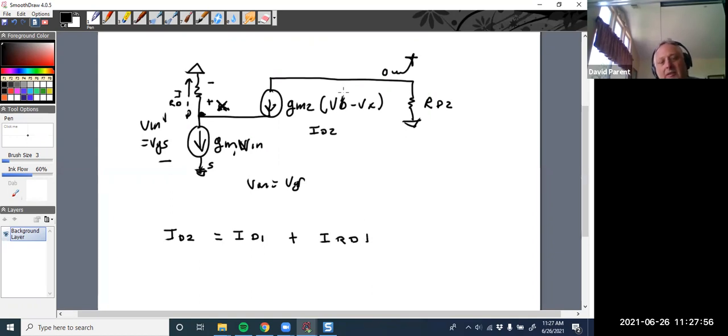So now what to do with this VB? Well, it's not an input or an output. With experience, I can tell that it's just some constant voltage they're using to turn the transistor on. If it wasn't, then they would tell you to find V out versus VB and V out versus V in, right? So actually, with this idea of small signal analysis, what's the derivative of VB if it's a constant? It's 0, right?